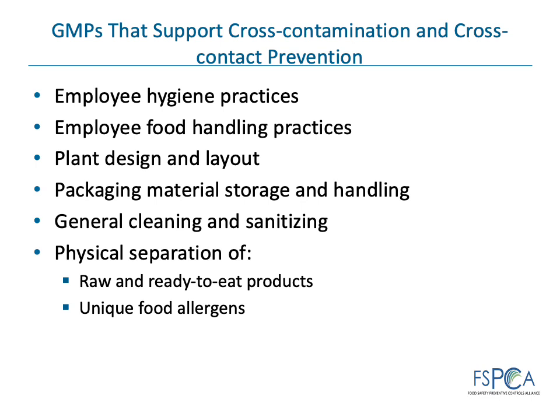Plant design must prevent potential contamination of stored ingredients and raw materials, food, and food contact surfaces, including separation of operations where contamination is likely to occur. This means separating raw product and unpackaged ready-to-eat product to avoid contamination. Similarly, separating foods that contain food allergens from those that do not contain the same food allergens helps to avoid allergen cross-contact. Food contact surfaces must be cleaned and sanitized, as appropriate, when contaminated.